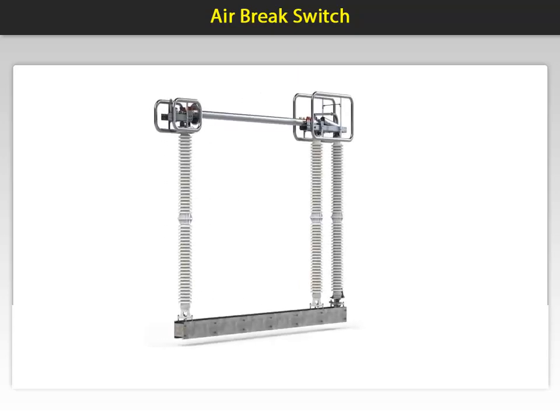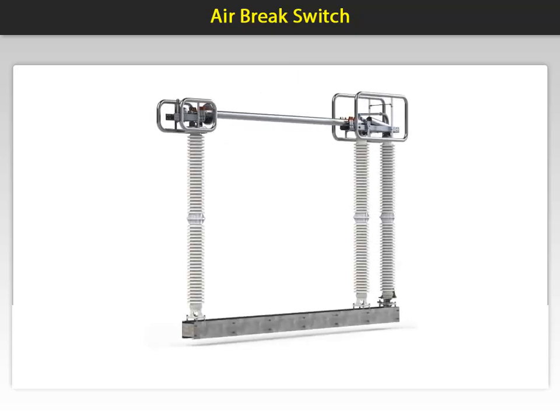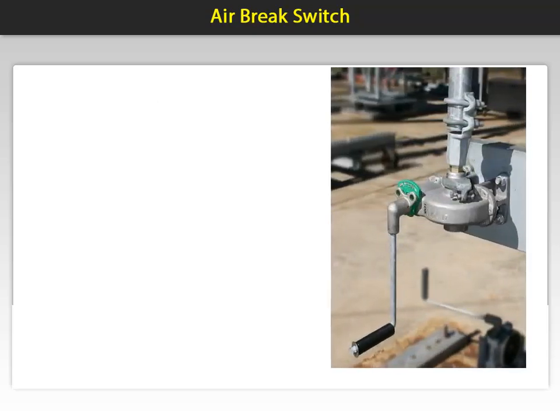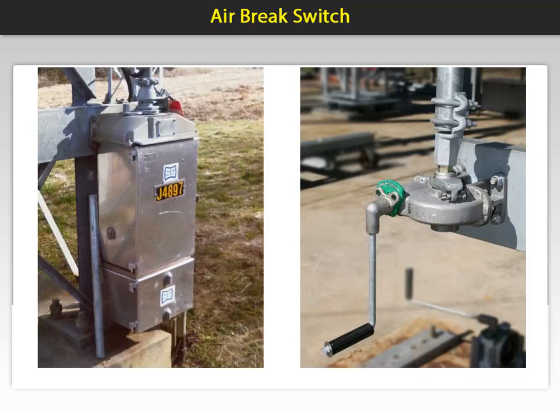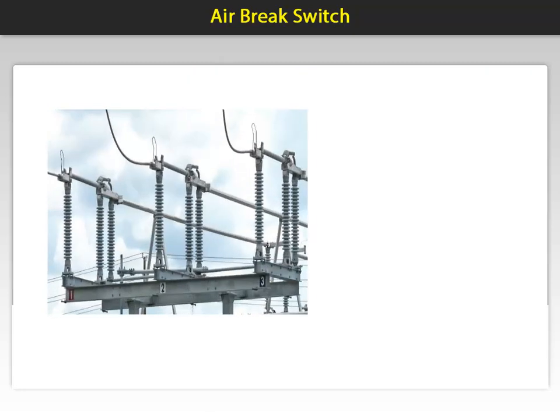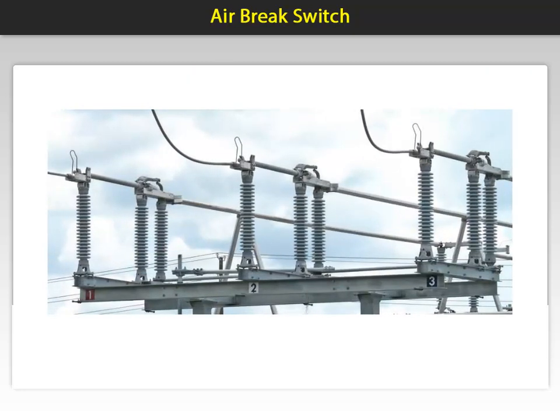It is necessary to isolate the circuit breakers, transformers and other equipment. One option is to use an air break switch manufactured by Southern States, seen here. This is a single pole but can be grouped with two other units for the required 3 poles. These are non-fused and can be operated with a manual crank seen here or with a motor operator seen here. The 3-pole group operated switch and mechanism is seen here.